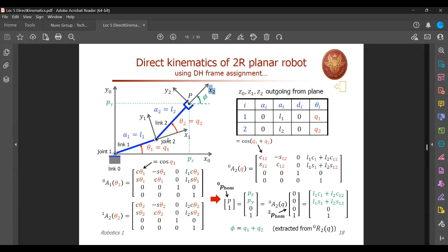Following the DH convention, immediately you can figure out, even before doing anything, that the alphas are 0. All the links are not twisted. Both of these links are not twisted. So alpha is 0. Once you prepare the DH table, remember, you are supposed to be able to look at a robot arm like this. Given the information, you are supposed to fill this DH table.